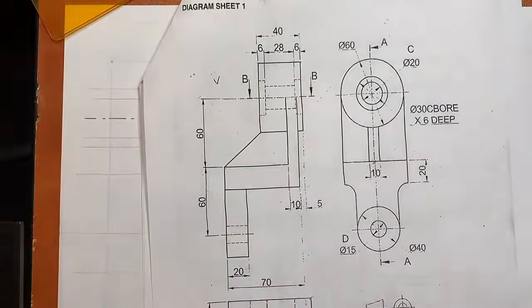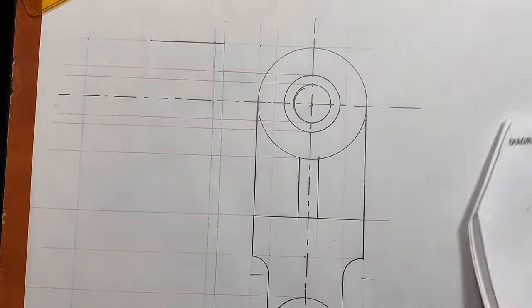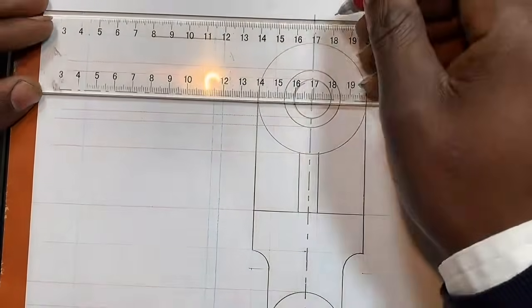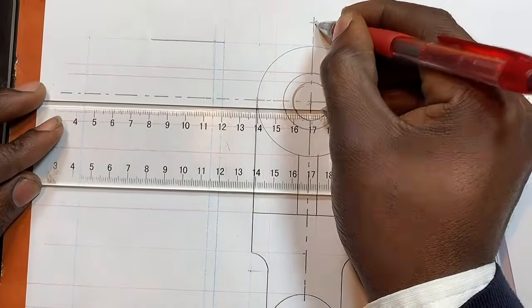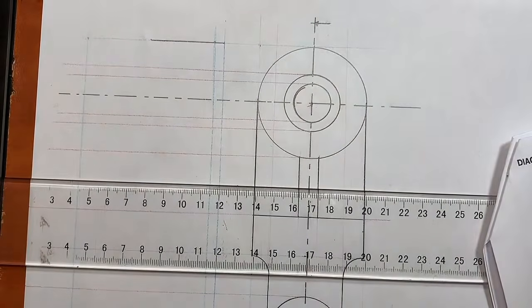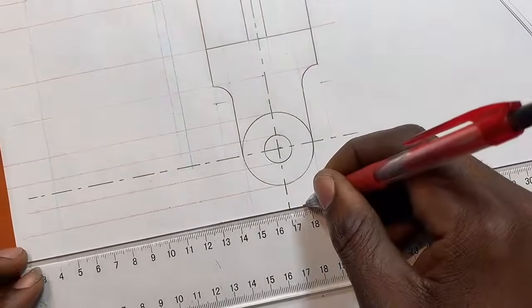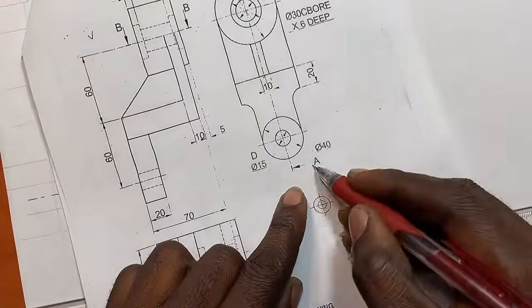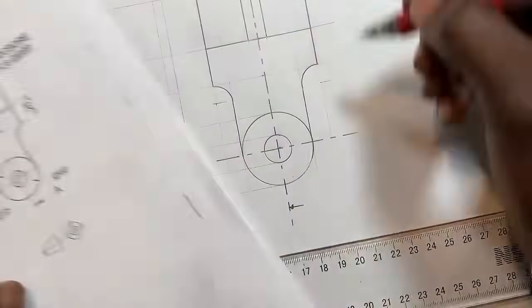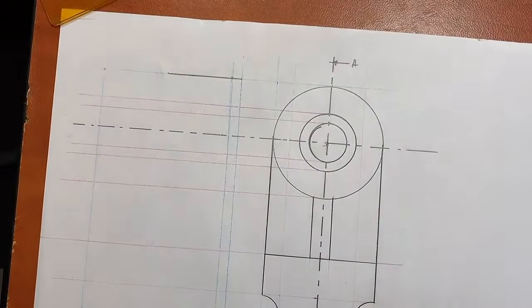You understand? Maybe before I even start to draw the left, let me have the cutting plane, which is this one. Double check the arrows. I normally used to say we draw what is being pointed by an arrow. So whatever is beyond the cutting plane, we consider it as an offcut. So there is the cutting plane that they are talking about. A. So this A is actually pointing at your front view.